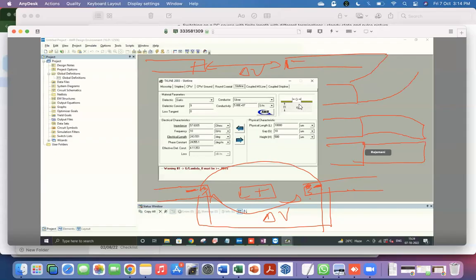And again, all of these have to be done very smoothly over a sufficiently long distance so that this ground plane now sort of falls out of action, and then you are only left with the original center conductor. So it was something like plus, minus, minus in the beginning, and now this becomes plus, maybe plus prime and minus prime. And then you can put your device across here. So this is something one can use if you need to excite a differential.